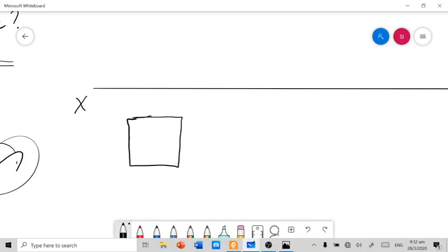The base side is 40 mm, and since it is a pyramid, it's going to have the apex. So we need to join the diagonals in order to show the slant edges, and the apex point can be named with the alphabet O, and the rest of the base corners may be named with alphabets.